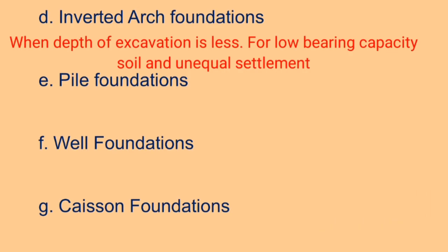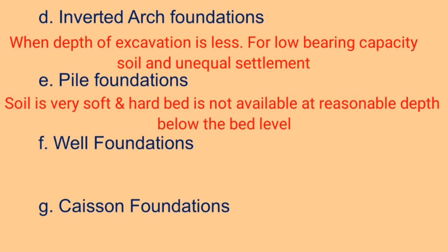Now, fifth one, pile foundations. This type of bridge foundation is suitable when the soil is very soft and the hard bed is not available at a reasonable depth below the bed level of the river.